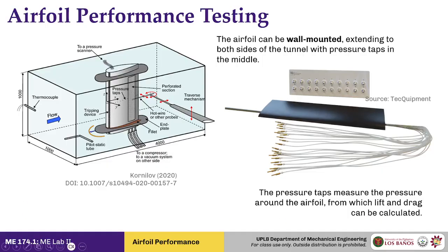So what you'd have here in this particular setup is that you'll have these little holes along the midpoint circumference of your airfoil. Now, for some pressure tap airfoils, you might be interested in holes here aside from the midpoint. But basically, the point of these taps is that you can connect some pressure tubing to those taps, and then you can record basically the pressure on that point of the airfoil. Now, the neat thing about this is that with this, you can actually develop an experimental pressure distribution along your airfoil.